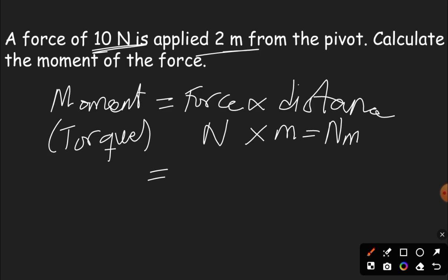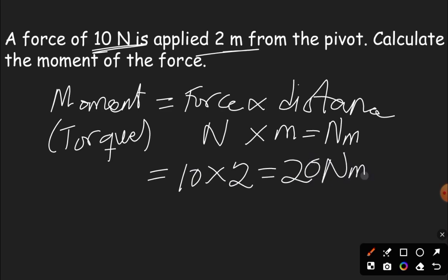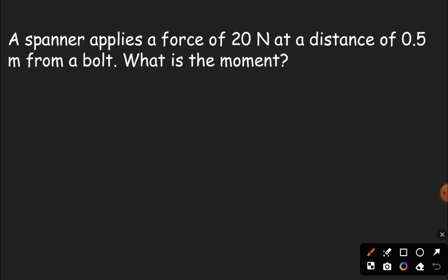So the force over here is 10 Newtons. So 10 multiplied by the distance, 2 meters. So you are going to have 20. So 20 Newton meters.